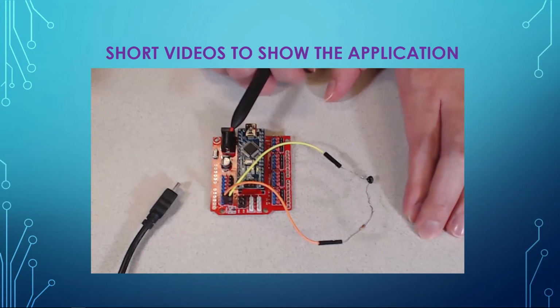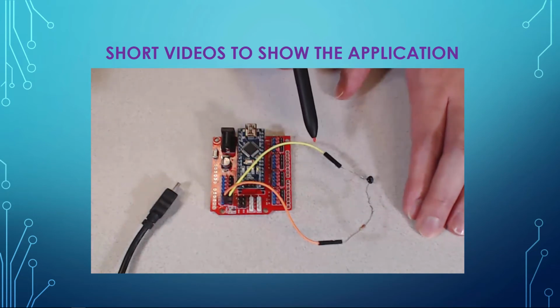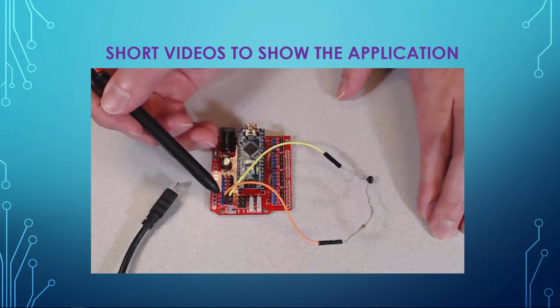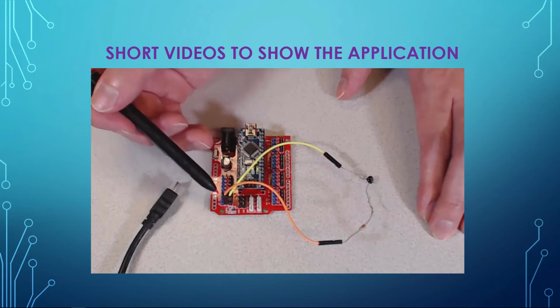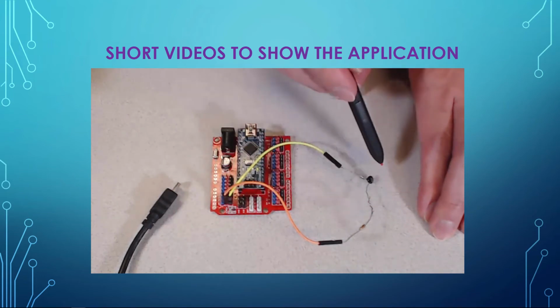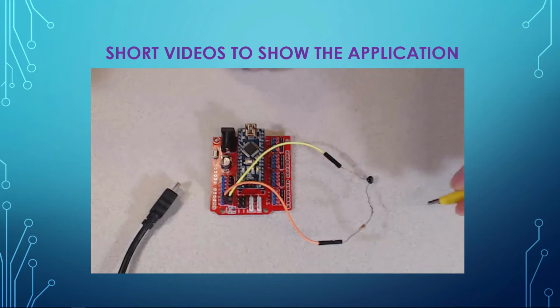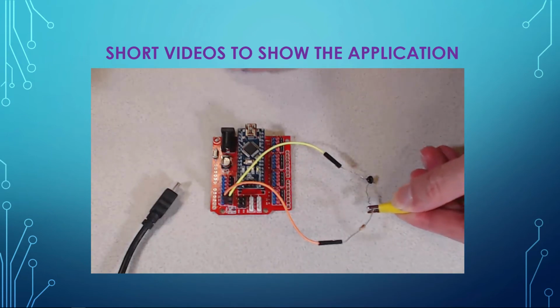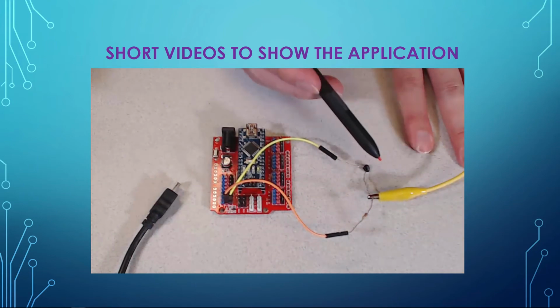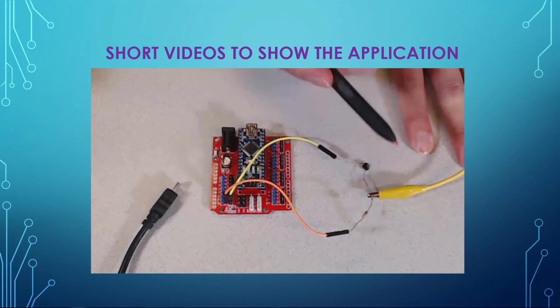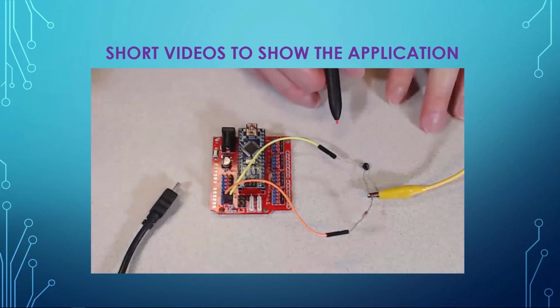As we all know, resistance cannot be measured directly, and this is why we need to use this voltage divider circuit. As you can see, these two resistors are connected in series with a power supply coming out from the red pins here, going up and then through this resistor to the temperature sensor and then back to the ground. So if we take a voltage measurement here at this node, then we can measure the voltage difference. From a known supply voltage and resistance of a reference resistor here, we can work out the resistance of the temperature sensor and in turn the temperature using the equation.